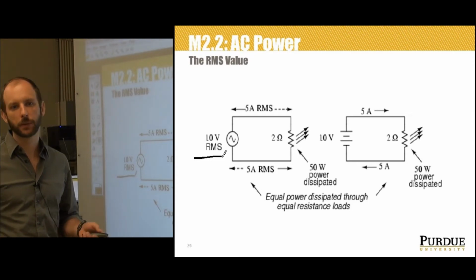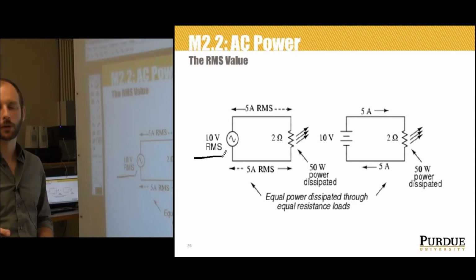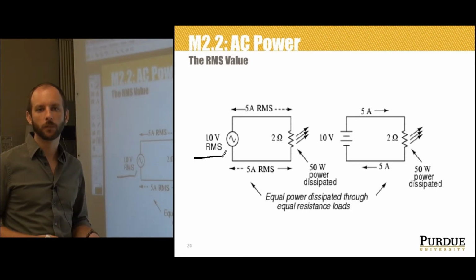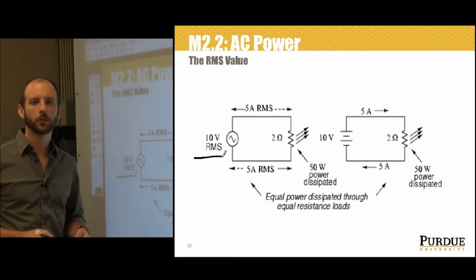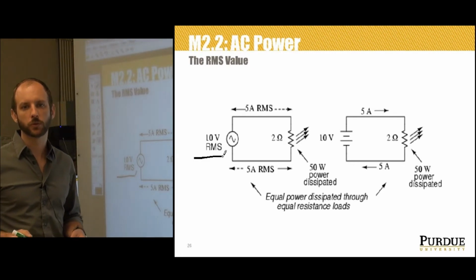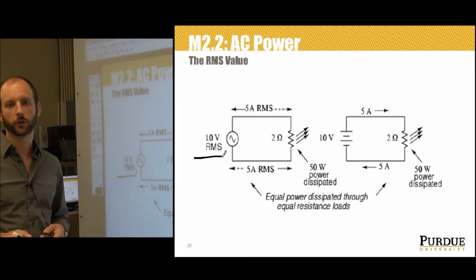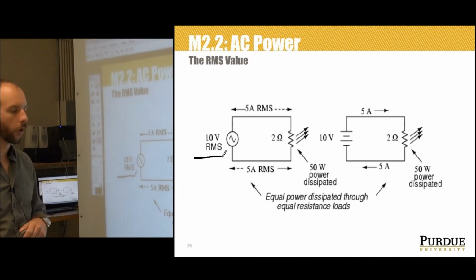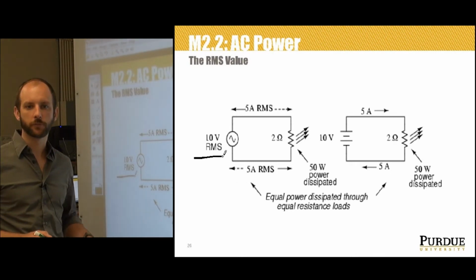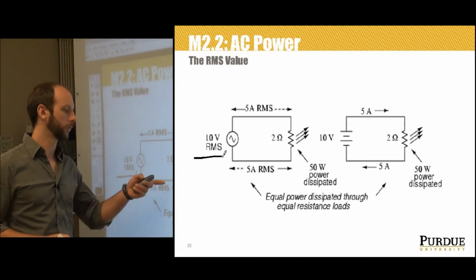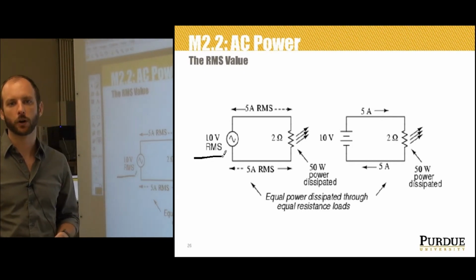For other considerations, peak measurements may be the best to employ. For example, when determining the proper size of wire, known as the ampacity of the wire, its ability to carry current, to conduct electric power from a source to a load, we use RMS current measurements. It's the best to use because the principal concern with current is overheating of the wire, which is a function of power dissipation caused by current through the resistance of the wire. And since it's a power dissipation issue, we use RMS.